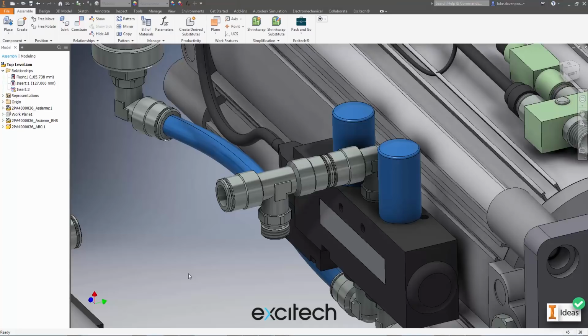lock all of those, which reduces some degrees of freedom and frees up some processing power, as Inventor doesn't have to compute these free to rotate bolts anymore. They're just fixed and grounded. So it's almost more of a performance enhancing tool, if anything else.